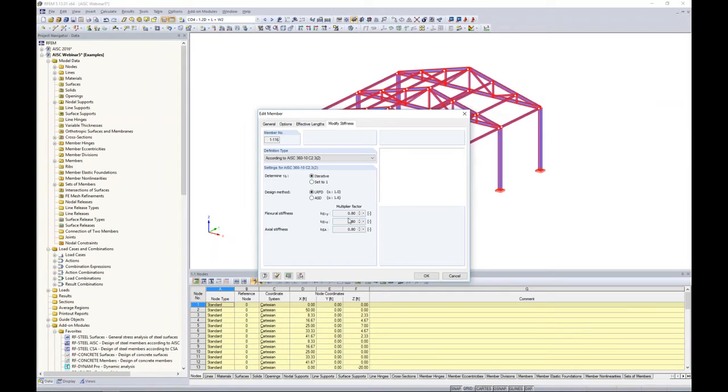The flexural stiffness and axial stiffness multiplication factors, that 0.8 factor will be applied here. The way that our program is set up, the gross area is something that's very easily known from RFEM, but the effective area is not determined until much later on within the steel module. So at this time, it's just a limitation of the program that we cannot account for slender members. Realistically, it's not too often that we're designing with slender members. It's definitely not unheard of, it's just not so common.